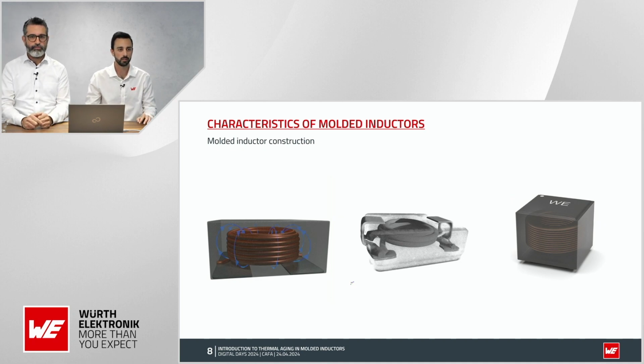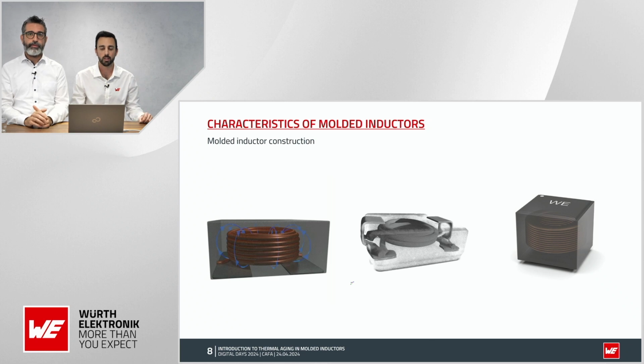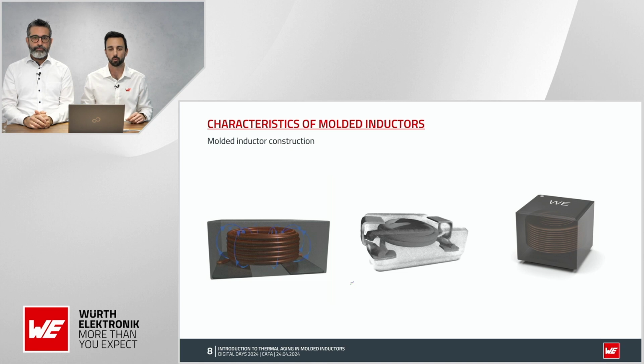As we said in the previous slide, we have several advantages using molded inductors. And now we will see a little bit what the main construction of molded inductors you can find in the market is. The ferrite inductors are constructed in a very different way. First, you need to manufacture the core separately, and then you do the winding around, and you have some extra processes of gluing to hold everything together, some welding, and maybe you have to add some base or clip. In the case of molded inductors, you do the other way around.